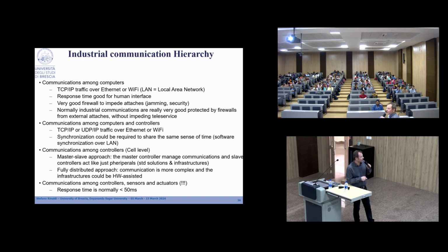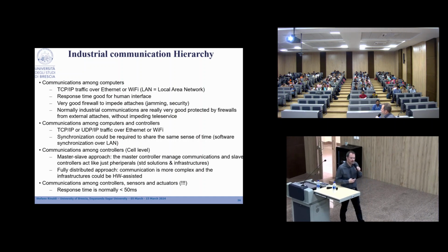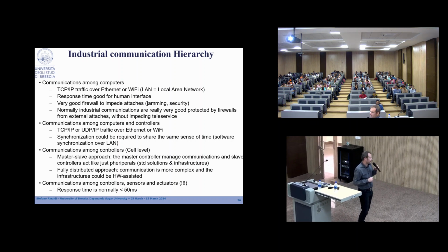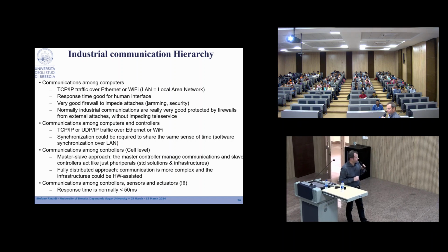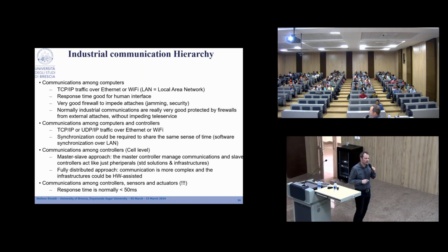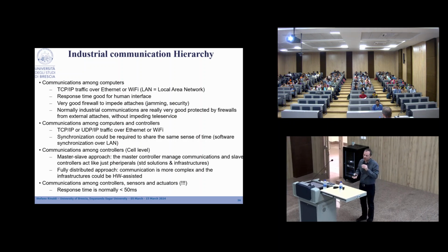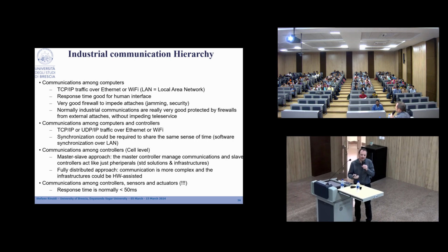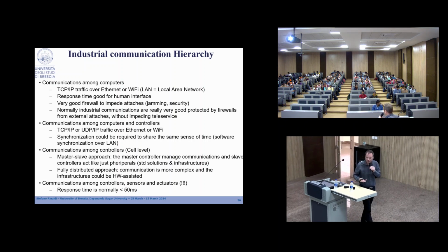Then we have the communication between computers and controllers, basically between the SCADA and PLC. Also in this case, we can use Ethernet and TCP/IP protocols, because again, at the communication level between SCADA and PLC, we don't need to respect real-time behavior, because we are just transferring information for monitoring purposes.